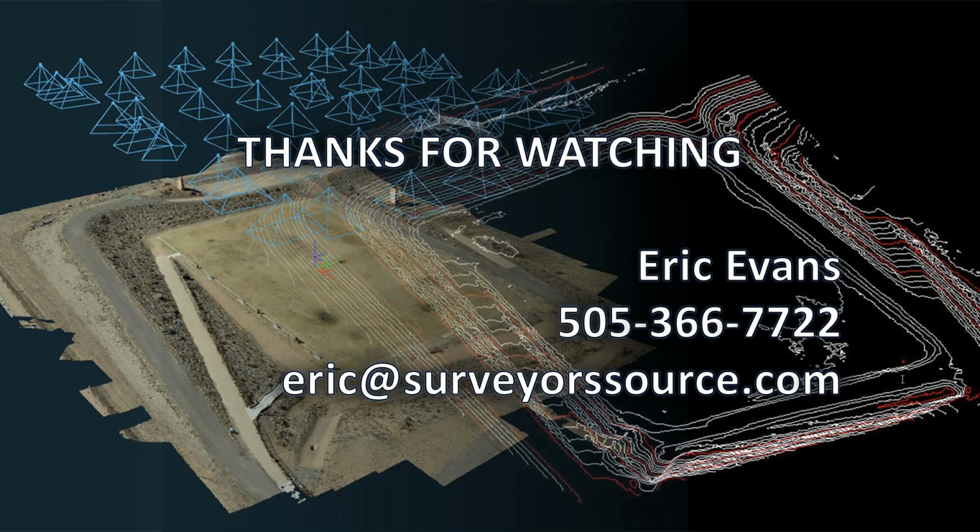And if you think that 1 meter or 3 feet is a lot for grid cell spacing, just compare that to traditional measurements where we usually just record 1 point per 5 meters. So it will still get a very good digital terrain model. So yeah, the main thing is just pay attention to the detail of the surface that you're trying to bring into Civil 3D or Carlson.